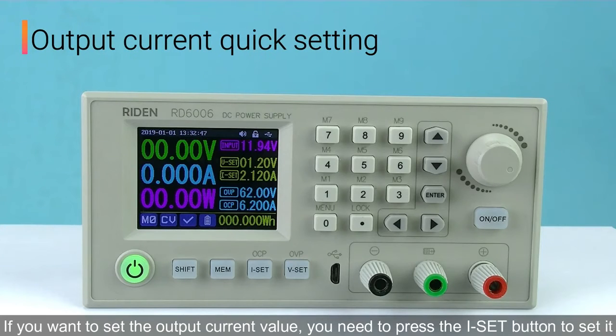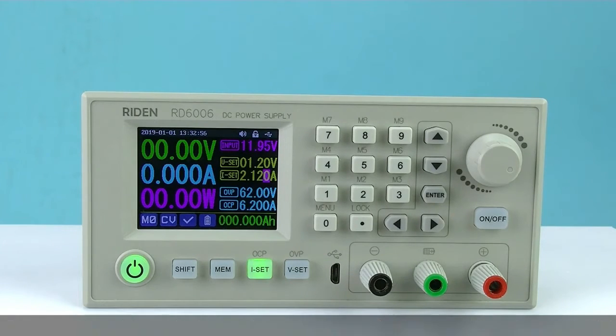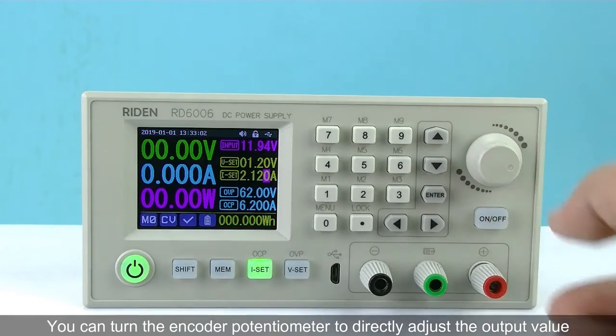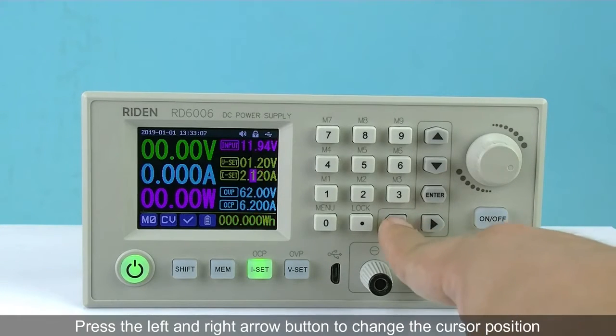If you want to set the output current value, you need to press the I set button to set it. You can turn the encoder potentiometer to directly adjust the output value. Press the left and right arrow buttons to change the cursor position.